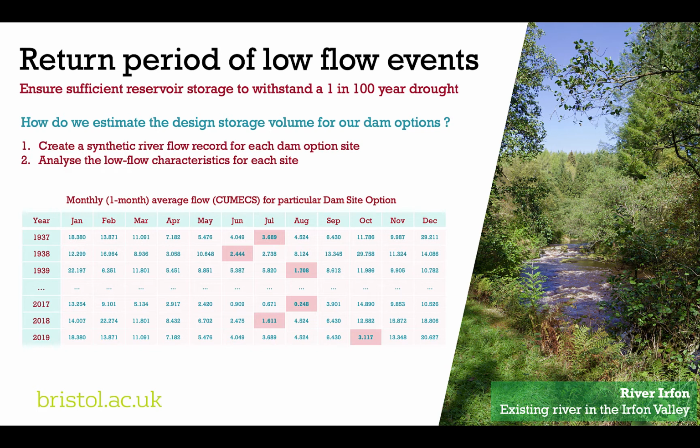But once you've done that for the 1 month data, you would then repeat that for the 2 month data. And so from our indicative table here, I've just highlighted where the 2 month minima would be formed from, and then you would repeat a similar return period and regression analysis. Now the slightly tricky thing here is that you don't necessarily know the crucial period of aggregation in months for which you're going to have to design your dam. And what I mean by that will become evident in a few minutes.